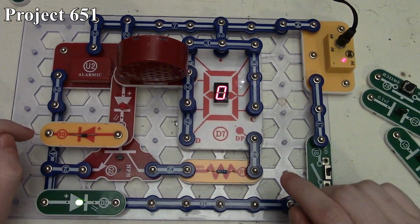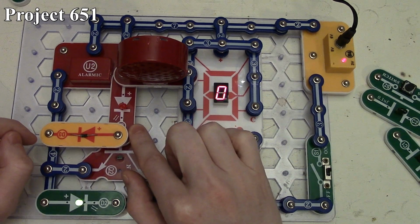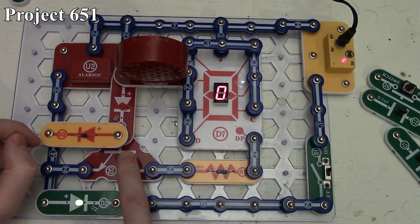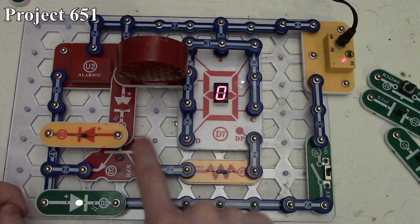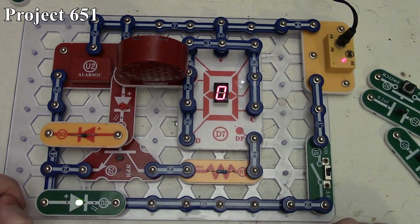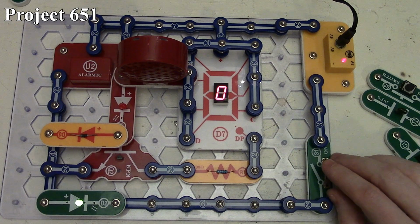When the alarm IC turns off, then the current is going back through our speaker through our red LED here, and we see it briefly turn on because of that. And because of it, the base of the NPN transistor allows it to turn on, and that makes our decimal point light up there briefly, and we can see the difference in current between when the transistor is active and when the alarm IC is active. And because of how it alternates there with the output of the alarm IC, that's how we get the different showing of both the 0 and the decimal point.